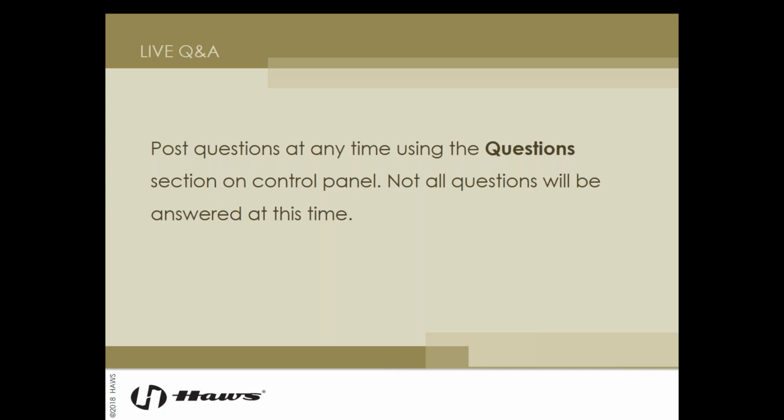Rodney wants to know if a facility has to remodel in order to comply with ADA. Well, normally ADA modernization requirements are triggered by a remodel. There is a 20% cost of the alteration exception allowed by the ADA. So if you're planning a remodel of an existing facility and you had questions about just how much of these ADA requirements you had to comply with, you could qualify for a hardship.